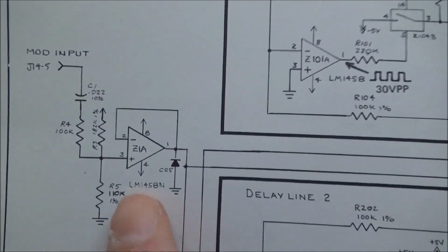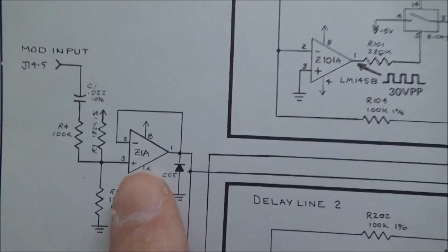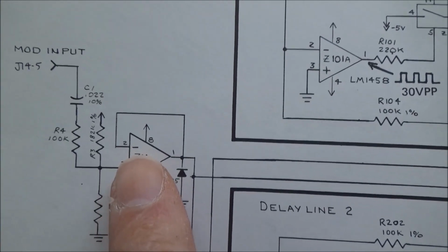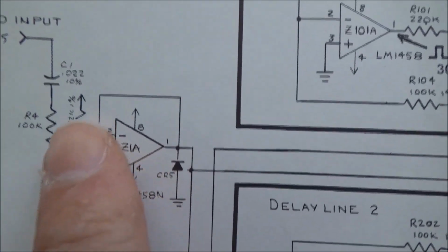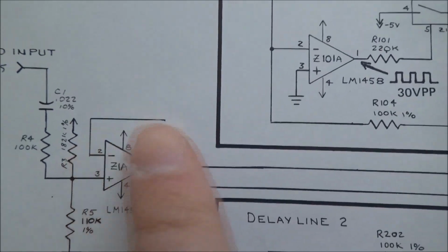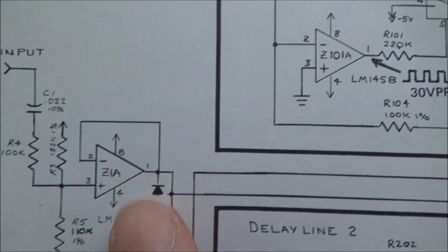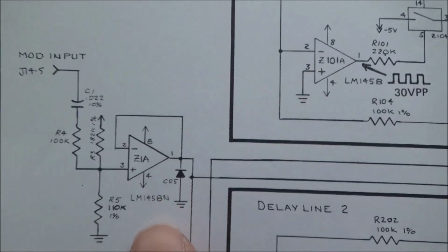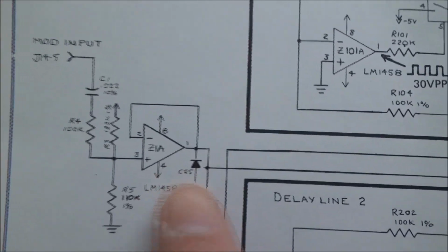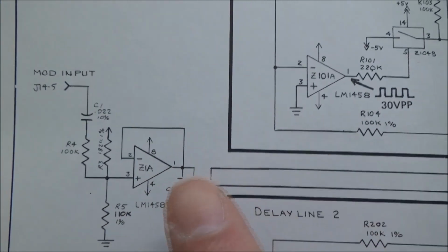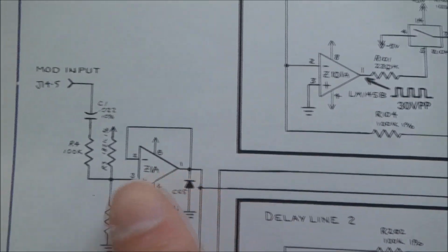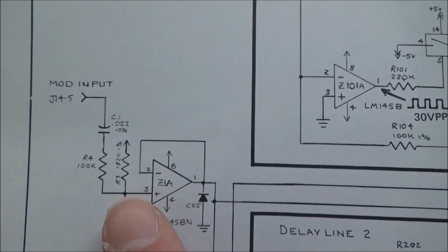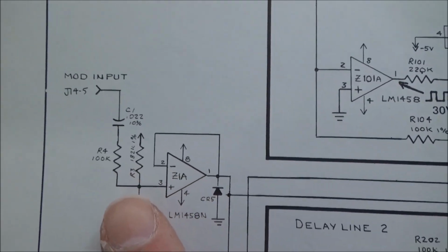When you have an op amp connected this way, where the inverting input, the little negative symbol, is connected to the output with nothing in between, no resistor or anything like that, that op amp is configured as a buffer. So basically it's allowing this phaser and everything that comes after it to do its stuff to this signal without putting any load or affecting the input signal in any way.